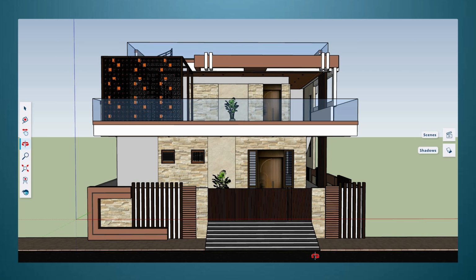So AI understands using 3 elements: the foreground element, the object and the background. My foreground element is the road, footpath and slope. The object is my building, and the background is going to have landscape and sky. For the sky, I have used a basic blue tint, and for the landscape, I am using a green color tint. This green color itself determines that this is going to be landscape, and the blue color determines that it is going to be sky. The landscape is something which Velocity itself provides using intelligence, but for the object, you need everything to be properly placed.